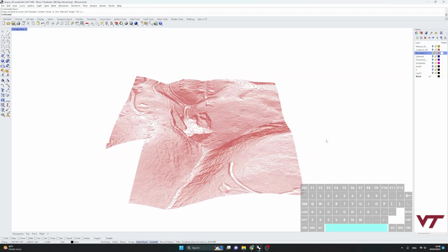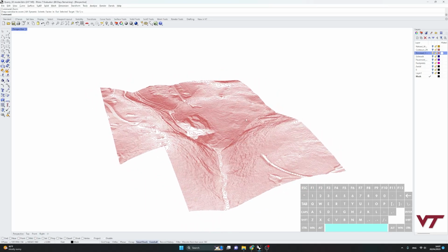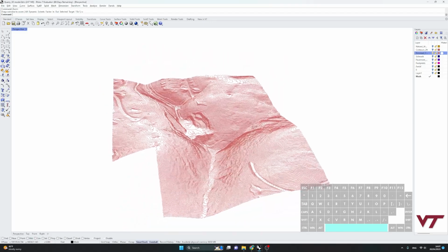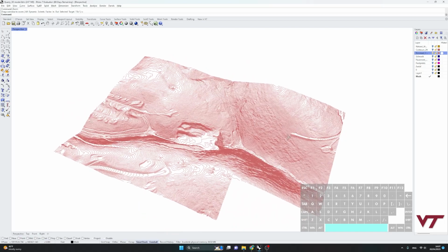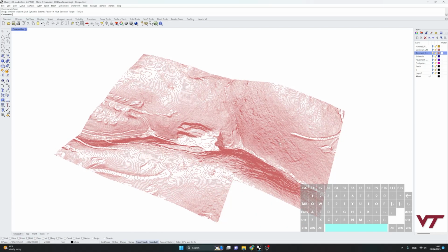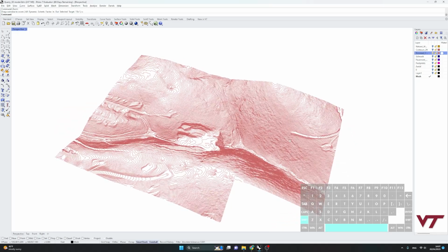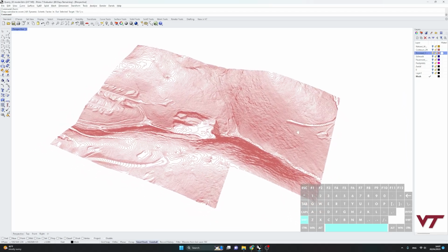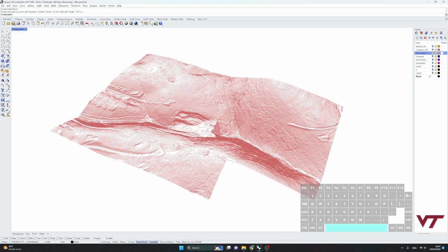If it does come in flat, it still has its elevation attribute within the line. You just might need to use ArcGIS to array it to put it into 3D space as opposed to 2D. But it's a very simple command using the set feature by 3D attribute, I believe, and it basically just spits that out like that.